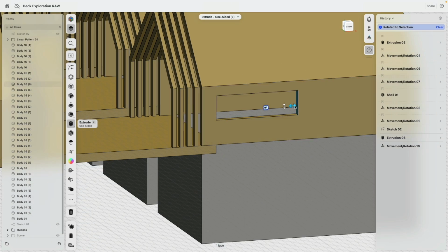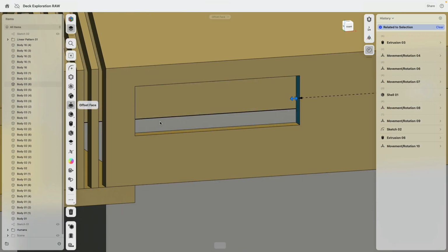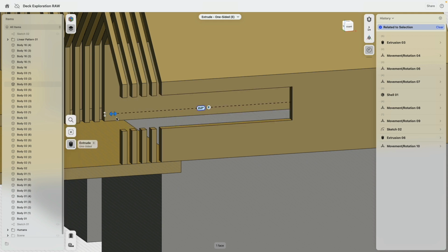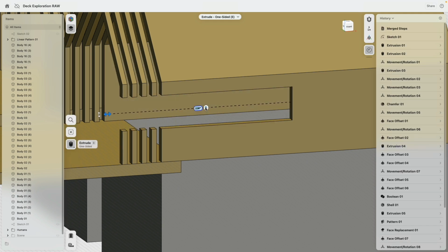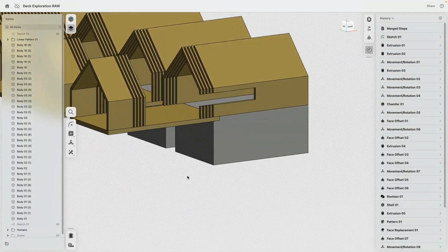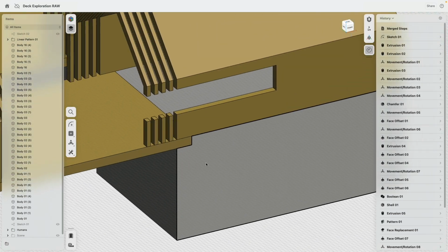We select that face and extrude, but wait, stop. We extrude this one quick through and we cut. Now you see how this automatically cuts. Cool. Okay. That's nice. Now the only problem is, okay, we have these floating elements. How do we make sure that's not going to be an issue?